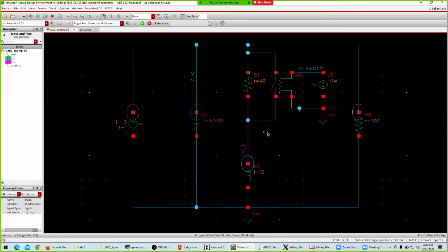Okay, now the current and voltages, all of those things are selected. Again, for Cadence, always remember whichever node we select for the current direction is always towards the component. So if I chose this node, then the current direction is this way, here towards the ground. If I've chosen this top node, it is into the component. If I choose the other node, which I can, then the current is towards the component, so it would be upward. All right. So I have chosen the current, I will hit the escape key.